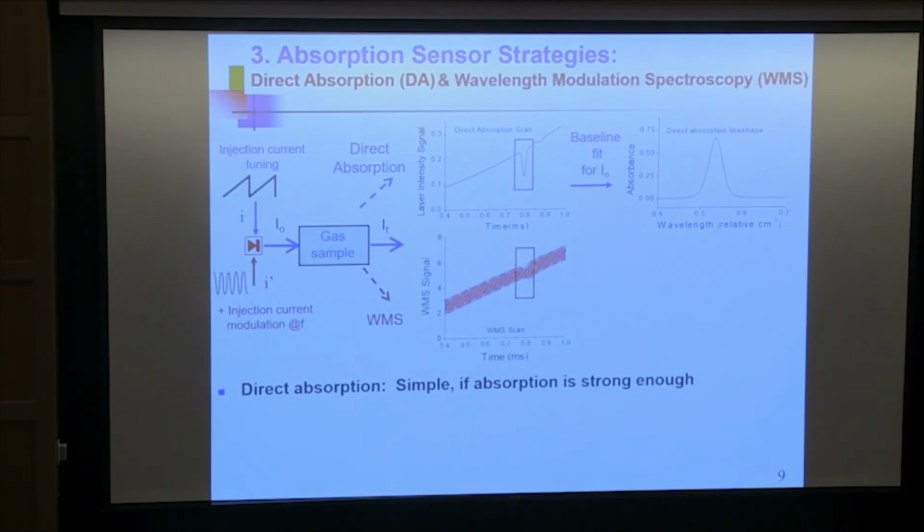It's called wavelength modulation spectroscopy, or WMS. And in that technique, you do the same thing, except you superpose on that scan very high frequency modulation. So you actually scan dithering as you go. And then if you take the transform, Fourier transform, you get something like this. And you can choose whether you want the 1F, the 2F, the 4F. You can choose which frequency. You do the analysis, Fourier analysis, and you record this.